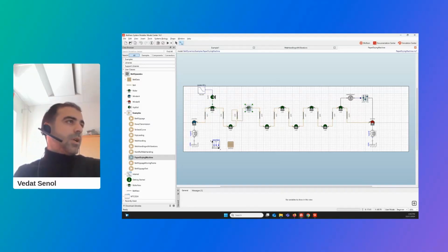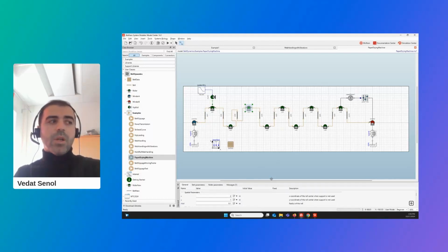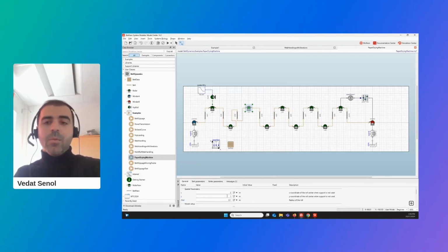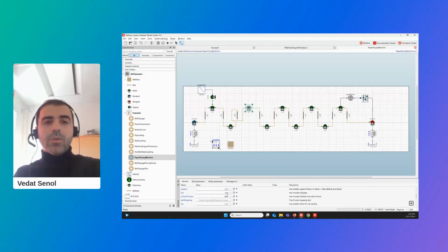Another nice thing, we are just creating these components and setting only the special parameters, which are like the dimension and the diameter, nothing more. If we want to increase the fidelity in the model, like adding nip roll, which can be done, we can just turn the corresponding flag in that component. And also, if we want to include slippage, we can just say, okay, it should be true in this scenario like here.